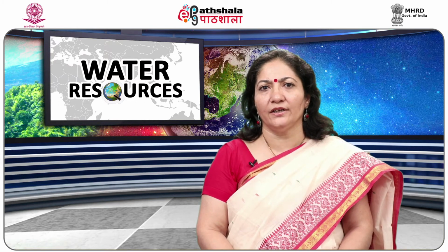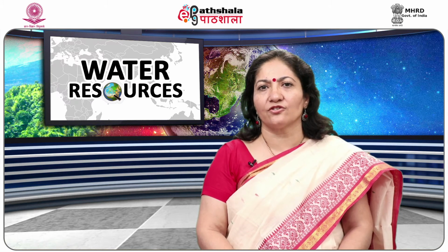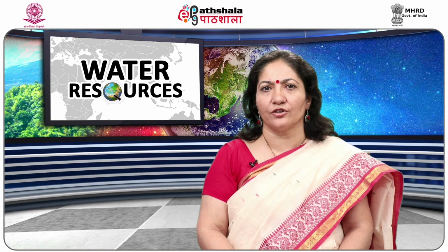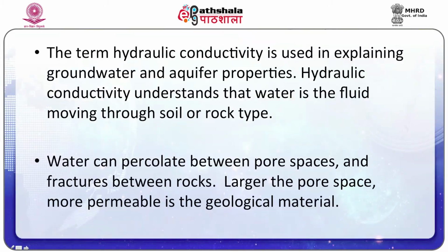Without the voids or interconnected pore spaces, the liquid or gas will not flow. The size of pore space and interconnectivity of the spaces help determine permeability. So, shape and arrangement of soil grains play the main role. The term hydraulic conductivity is used in explaining groundwater and aquifer properties. Hydraulic conductivity understands that water is the fluid moving through soil or rock type.